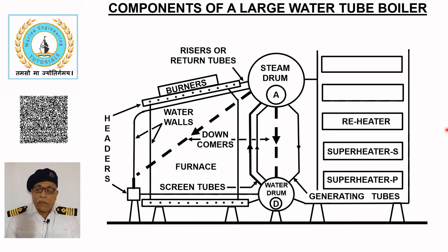Reheater. A reheater increases the steam temperature after it has expanded in the high pressure turbine, preventing moisture formation and blade erosion in the low pressure turbine. Reheaters may be internal, that is within the boiler, or external near the turbine.